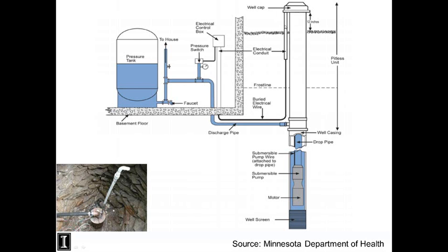It eliminates the need to have a well pit, and here's a picture from, I believe, a Pennsylvania publication. I didn't put a source here, I apologize. Of a well in a pit. You have a large rainfall event. This looks like it was originally a hand-dug well, maybe, that they put a drilled well inside and filled it in. This is susceptible to flooding, all those sorts of things. And so it's much better just to extend this pipe to the surface, fill this in, and provide a safe area around your well